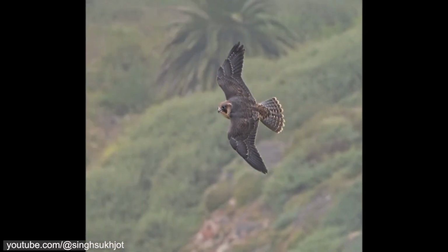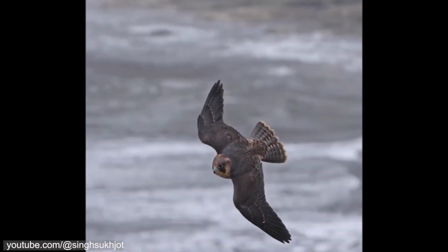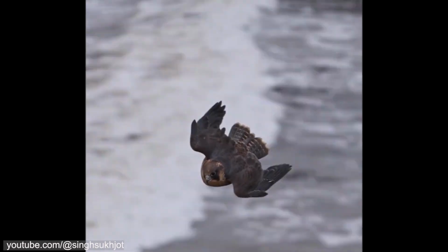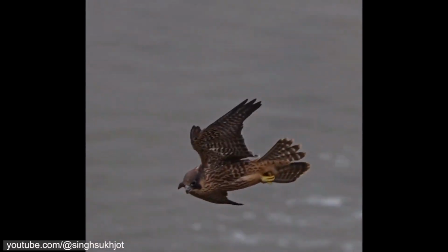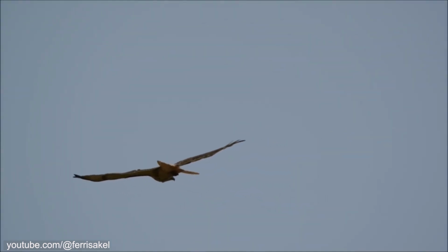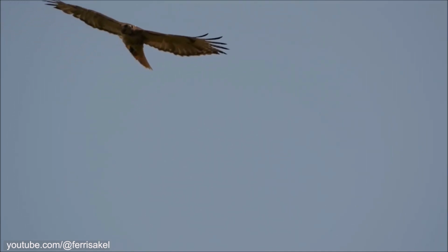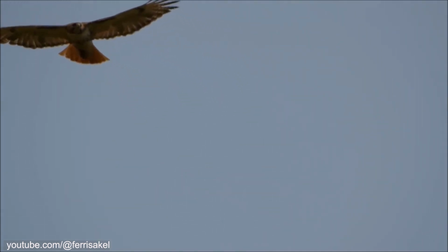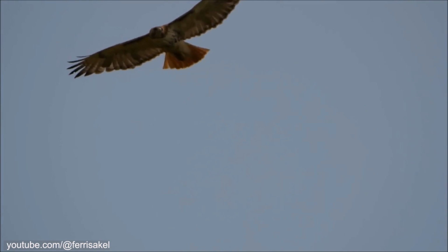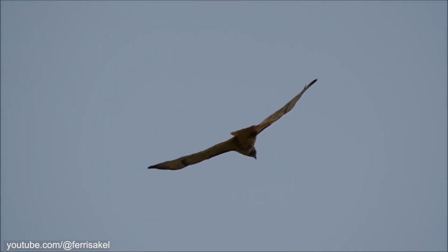To initiate a turn, birds mostly use asymmetric wing-morphing control techniques to roll their bodies and thus redirect the lift vector to the direction of the turn. However, when soaring, raptors can execute slow and steady banked turns without any observable wing movement, other than twists of the tail. Although tail twisting can compensate for adverse yaw, how raptors use only tail twist to perform banked turns is not well understood.